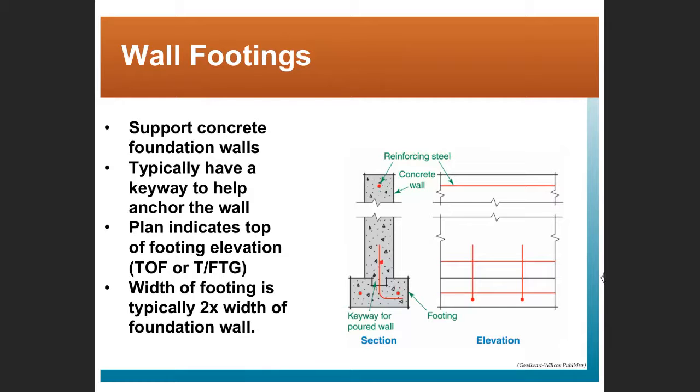We looked at plenty of details for foundation walls or footings. Typically there's a keyway or something that ties the footing to the foundation wall. We have our rebar in there. Width of the footing is typically twice the width of the foundation wall. That's a good rule of thumb.